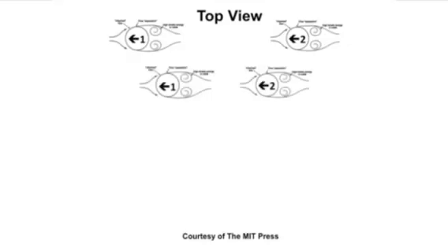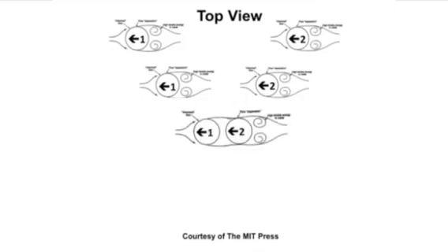Back here is rider 2. Since rider 2 is so far behind rider 1, rider 2's aerodynamic profile will look exactly like rider number 1's, equally as bad. Now as rider 2 gets closer to rider 1, at some point rider 2 will get into the slipstream of rider 1. And now you see quite a difference, because now rider 1's slipstream has effectively been extended past rider 2, so there's no drag behind rider 1 at this point. It's for this reason that drafting is faster.